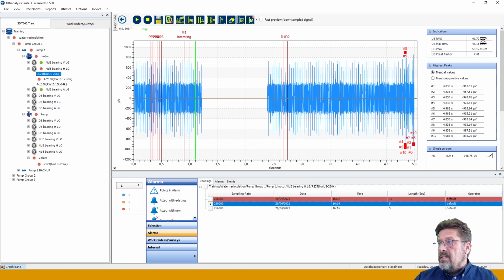Of course, my RMS has changed. So it's effective immediately. It's telling you, okay, the rest of the signal, including this part with amplitude 0, is now 41.72. It can happen sometimes that you have a good signal, you have good data, but unfortunately you dropped your keys on the machine during the measurement. So you can actually take this small part in time, remove it out and say, okay, everything else looks fine. So all the bad numbers are coming from this mishap during my measurement.